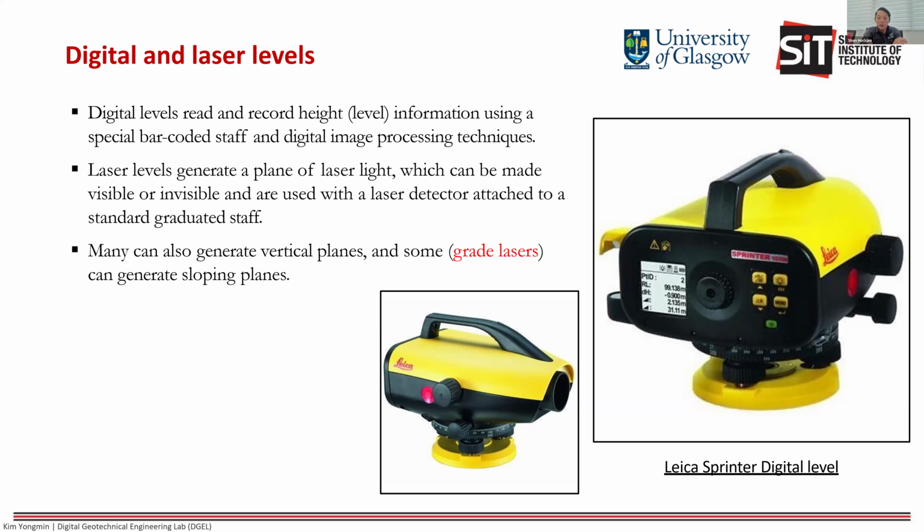These are very good for formwork and for road works when you want to understand gradient and surface runoff control. If you use a grade laser during road paving, you set a correct slope for your runoff into the nearby water catchment areas. These instruments typically increase the efficiency, consistency, and the safety on site.